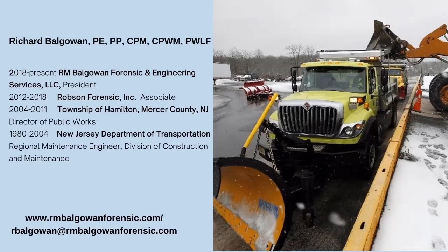I could go on for a long time here, and I know I'm jumping around a little bit, but another component of that GIS, AVL winter snow and ice control management system that we used also included what was called a maintenance decision support system. This was also based on that best practices manual I mentioned earlier, the manual of practice for an effective anti-icing program. Depending on the weather conditions being reported into the system, and including your forecast information, it would advise you what you should do, following these best practices guidelines.